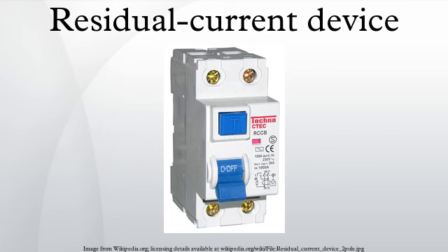This system, with its associated circuit breaker, included overcurrent and short-circuit protection. In addition, the original prototype was able to trip at a lower sensitivity in the presence of an interrupted neutral, thus protecting against an important cause of electrical fire. Following the accidental electrocution of a woman in a domestic accident at the Stilfontein gold mining village near Johannesburg, a few hundred FWJ 20 mA earth leakage protection units were installed in the homes of the mining village during 1957 and 1958.